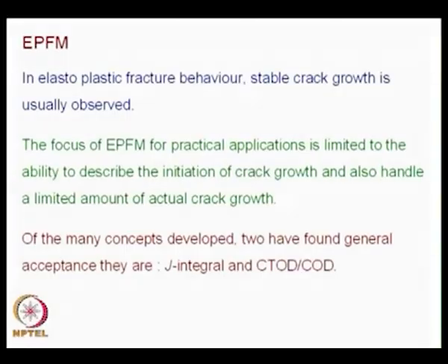Some crack growth you can possibly analyze approximately. If there is crack growth, you have a problem. Unloading takes place, and these approximations are not going to be valid. Many concepts have been developed in EPFM. Of the many concepts developed, two have found general acceptance. They are the J integral and CTOD or COD.